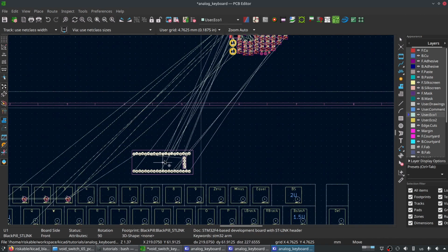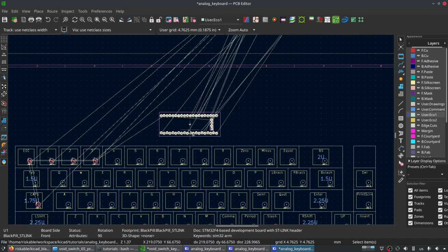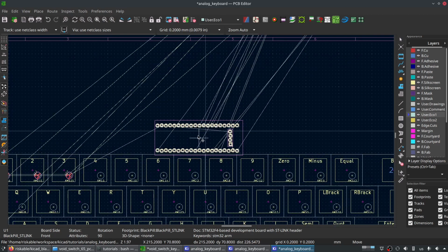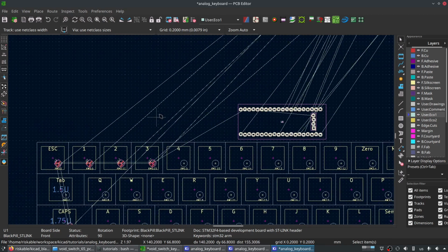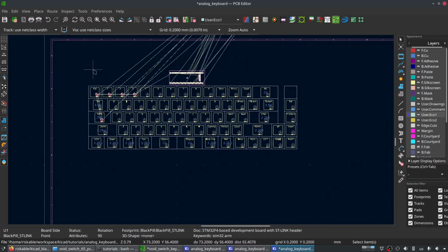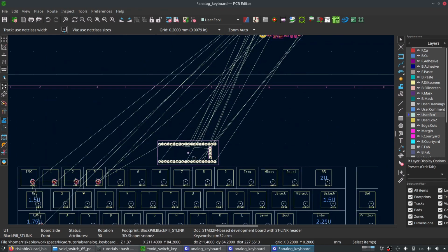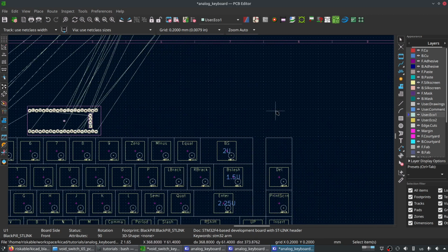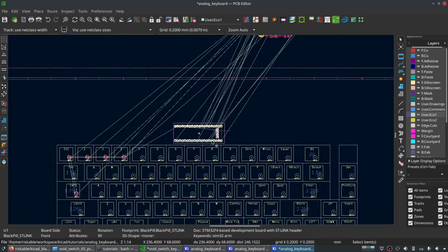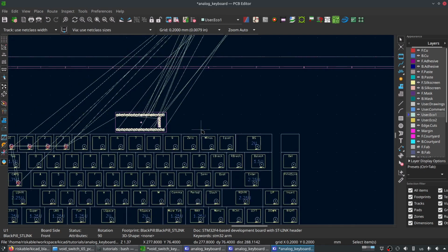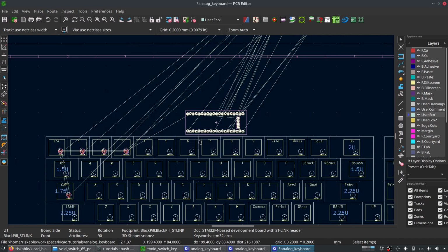And one last detail I'd like to add here before I start moving all these Hall effect sensors into place is the black pill board. How do I say this? It takes up some space, right? So if we put it up here, and we draw our outline of our board like I did in the tutorial, it's basically wasted space up here. Now, normally what I do is I break out all these extra pins and then set up headers over here so I can use them for things like hooking up relays, sensors, quick connectors and all sorts of fun things. And I'll try to use that space efficiently, maybe even put a buzzer up here, but it's really not necessary.